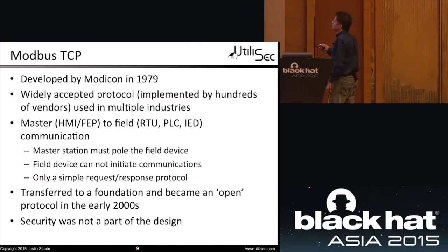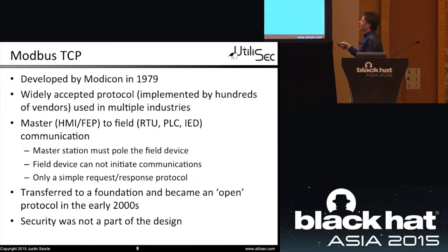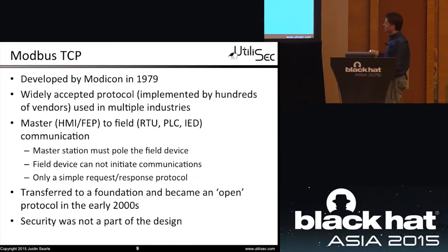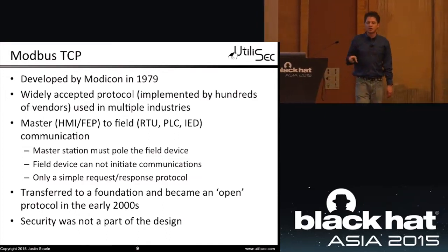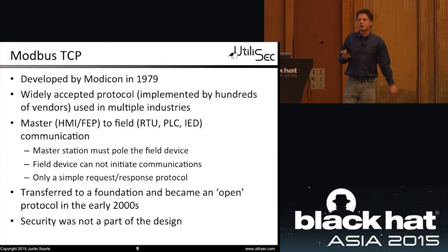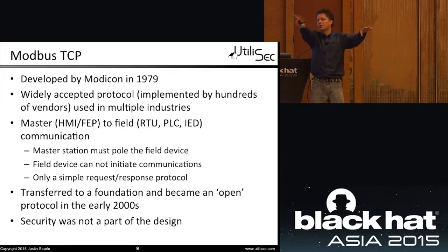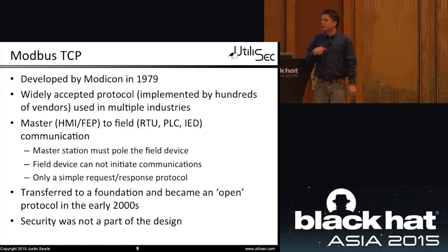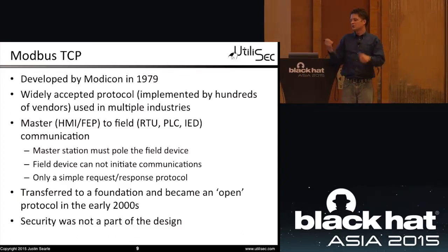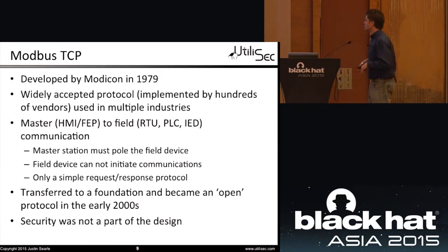It was proprietary before the 2000s, and it became an open protocol in the 2000s. Now it's very popular. There is no security whatsoever anywhere in Modbus. There's no encryption. There's no authentication. So you could have a master server talking to 1,000 different field devices, and if you can get on that network, you can use any of the tools that we'll be playing with today and send a control signal out to a field device and change some value in there. And that field device will automatically do it for you. No security whatsoever is built into the protocol.